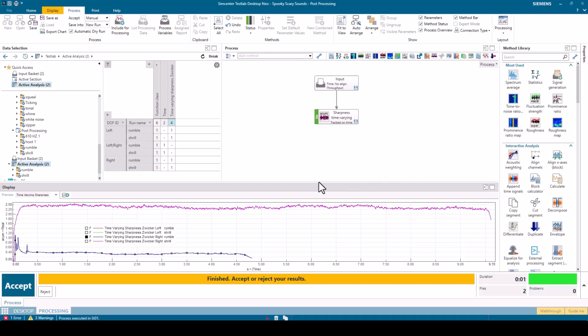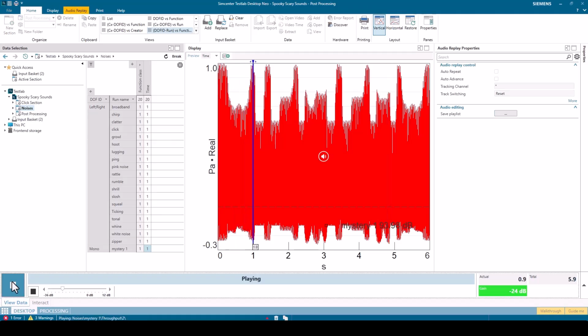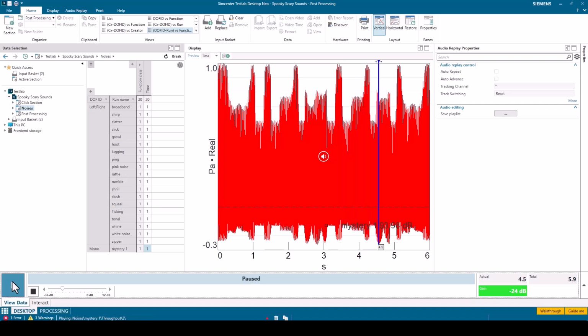Now, last thing, we have a mystery sound. This looks pretty chaotic, but let's just take a listen. Pretty loud and electronic. Now, if I were an engineer trying to analyze this sound, probably the first thing I would do is just look at an FFT. It's not a transient, so we could probably start there. And because this sound, I know for a fact, is going to form something cool, we're going to look at it as a color map.